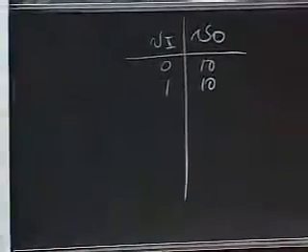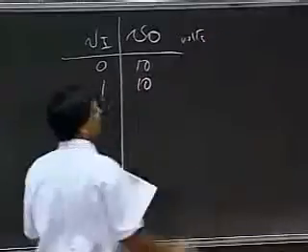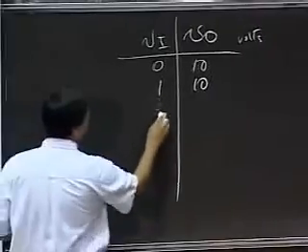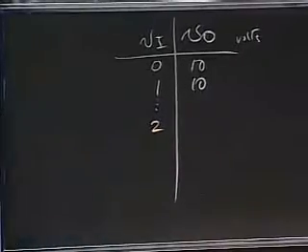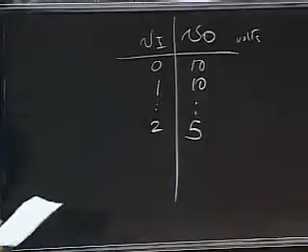So all the way up to 1, my output V is 10; all units are volts. I come down to 2. If I plug in 2 for Vi, 2 minus 1 is 1, so it's 1 squared. 5 times 1 squared is 5, and 10 minus 5 is 5. I get 5 out here.